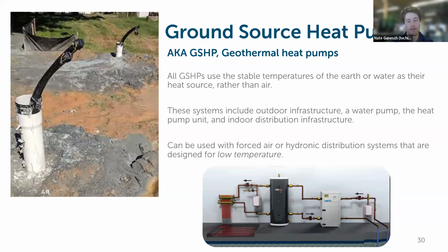A water pump for pumping that liquid through the wells underground. The heat pump unit itself, and whatever your indoor distribution infrastructure is. I want to tag that one of the helpful things about these is that they can be designed to work with either a forced air system, like a furnace or a ducted heat pump, or hydronic distribution, like an air-to-water heat pump or a boiler.